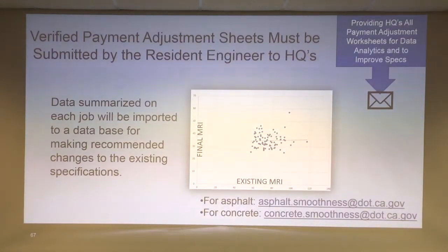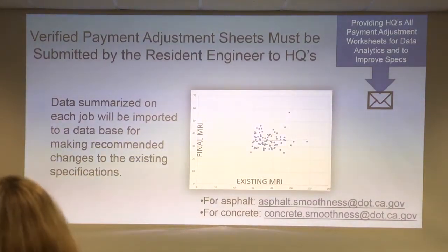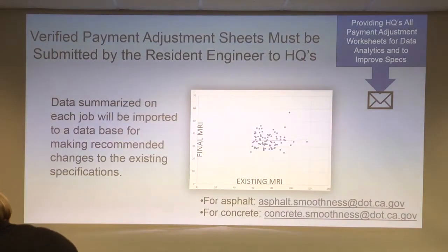When they're trying, they can pave smoother. When they're not trying, they don't need to pave so smooth. In the past, a lot of our projects just had a straight edge spec on it. It was kind of like they know the RE's not going to get out on his hands and knees and push a straight edge through the whole project. We're measuring every project now for smoothness, so they have to pave smooth. There's no other way around it now.